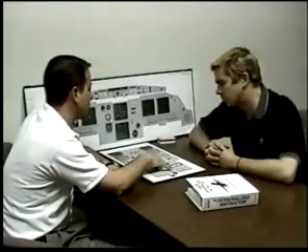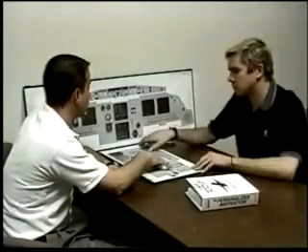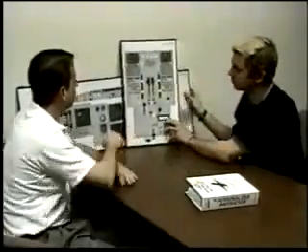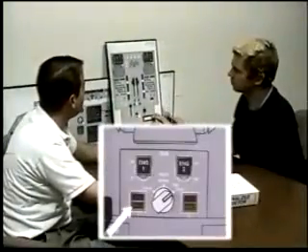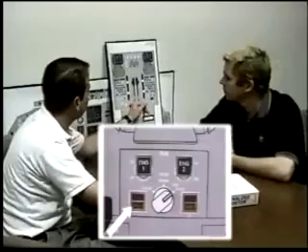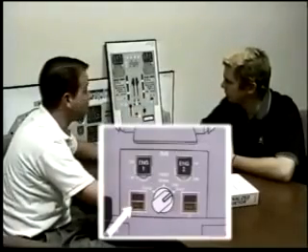You went from mode select normal to ignition start. You look for your parameters, and you suddenly get a fault light on engine 1 master switch, but both engine master switches are off. If I get a fault light, for instance, in number 1, that means there's a disagreement of the FADEC channel A and B with regards to the high pressure fuel valve.